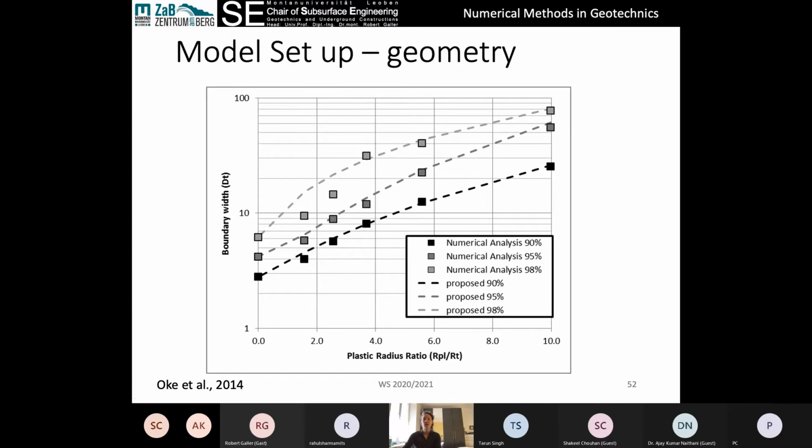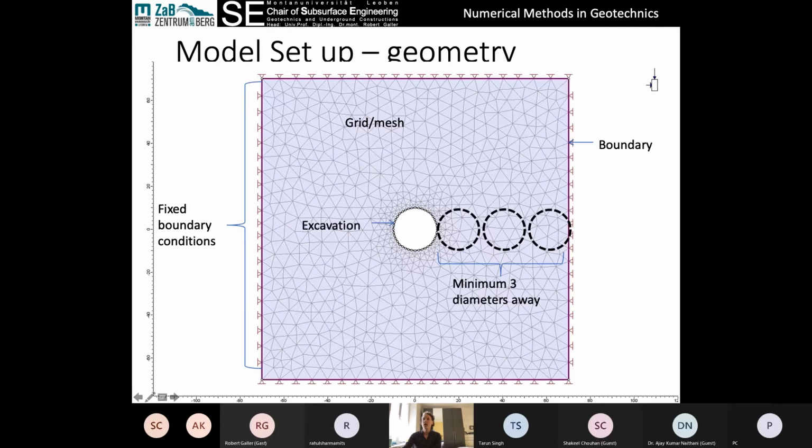And the reason that we have to do that is if we come back and look at this model here, oftentimes weird things are happening with the stresses, especially at the model boundaries. The reason is that there's a mathematical solution to the stresses in this element, and there's no way for the stresses and the displacements on these nodes to be shared in this direction.